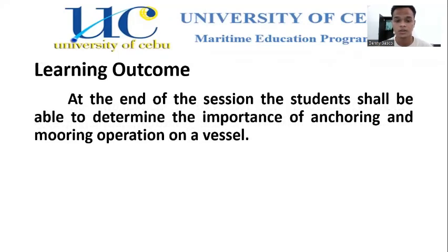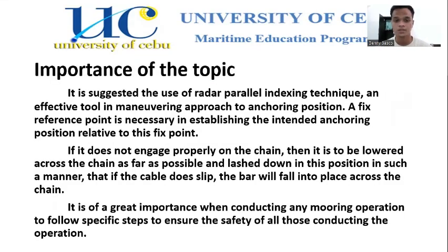Learning outcome: at the end of the session, the student shall be able to determine the importance of anchoring and mooring operation on a vessel. Importance of the topic: it is suggested to use the radar parallel indexing technique, an effective tool in maneuvering the approach to the anchoring position. A fixed reference point is necessary in establishing the intended anchoring position relative to this fixed point.